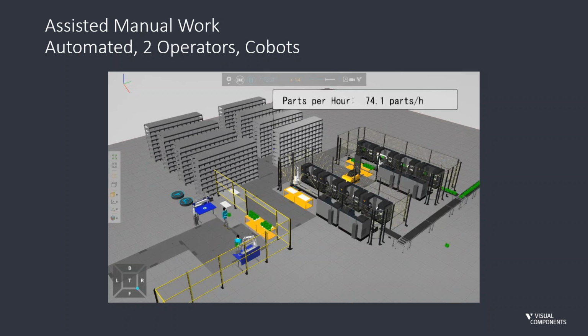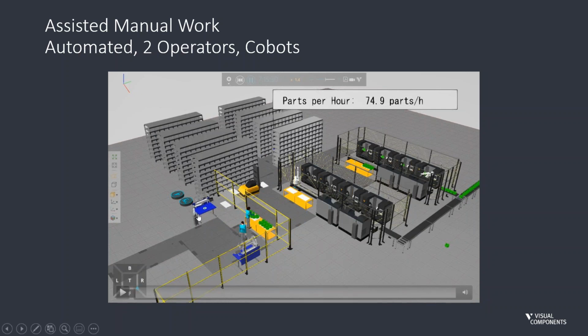And it could be holding some parts, picking some parts, even doing some basic assemblies or deburring activities or different kind of things. And in this scenario, we have done a couple of steps where we then increase the output from 54 to 75 parts per hour without any other changes. And this is actually a change you could make happen in a short period of time, something you could implement on the shop floor rather quickly.